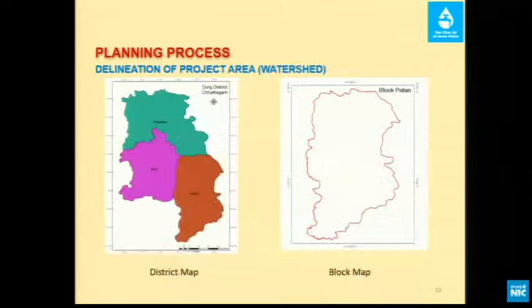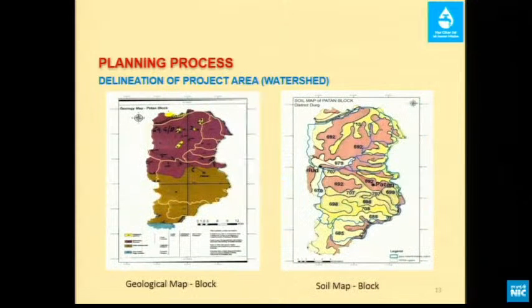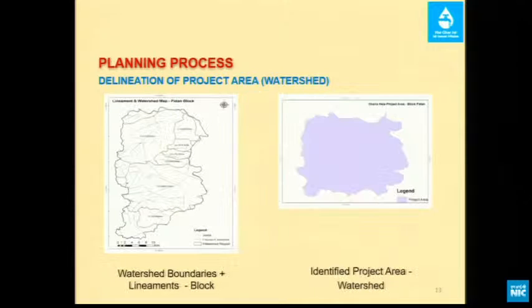Here, I have taken up one district, one block, and these are georeferenced. The block pattern consists of 4 topo sheets. These are the surroundings available. I combine them, and similarly 8 are combined and georeferenced for that block. These are the soil conditions, to ensure whether my soil is permeable enough to infiltrate and ensure groundwater flow.